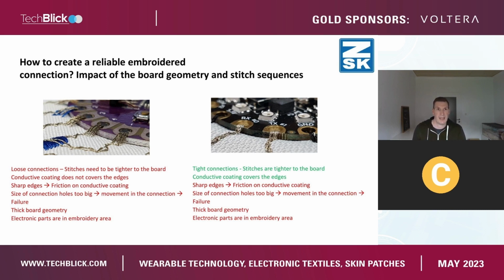What we have witnessed in the past is loose connections, where, for instance, the stitches needed to be tighter to the board to obtain the necessary surface conductivity, or even sharp edges of the boards damaged the yarns. Often the board geometry was quite thick, so it wasn't really flexible. And often it ended up in failure.